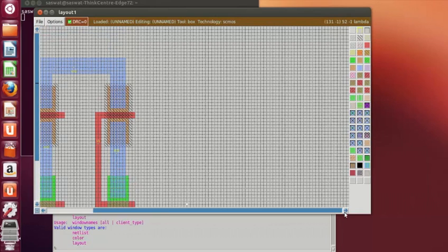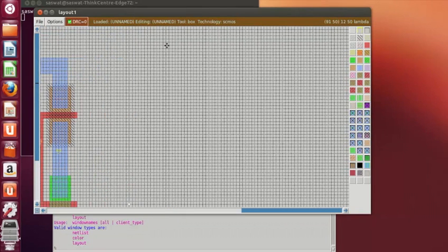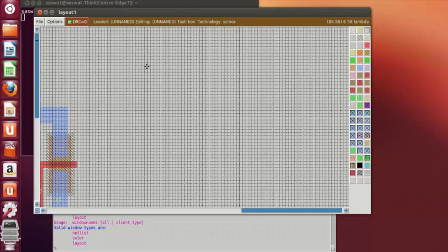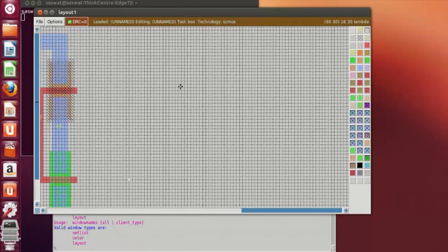in order to draw the transmission gate, in transmission gates, the PMOS and NMOS are placed in twisted form, but not like that in the twisted diagram. The gate of the PMOS is faced upwards and the gate of the NMOS is placed downward rather than facing each other. So let's draw the transmission gate. One will be placed up over here and one will be placed below.